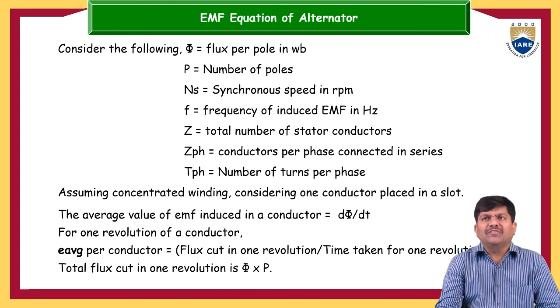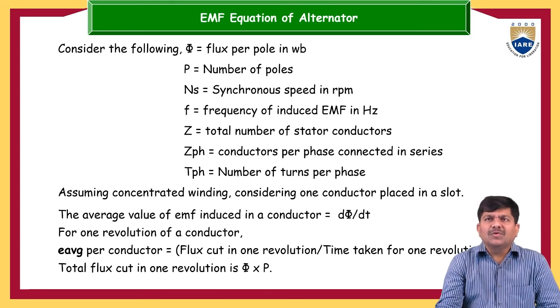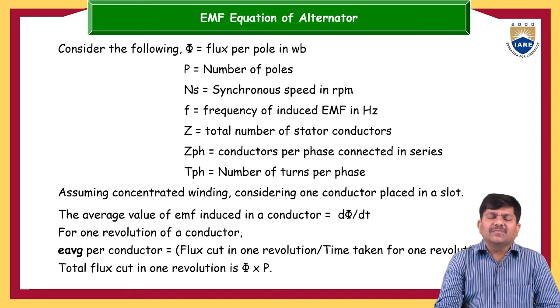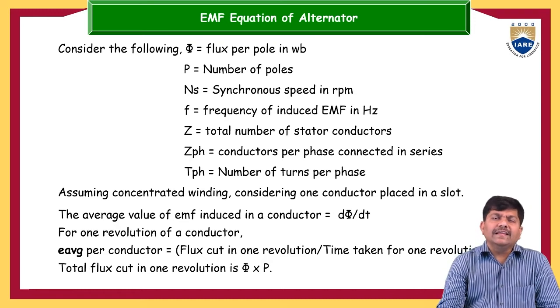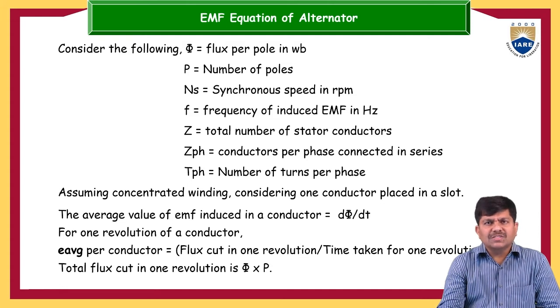F is the frequency of induced EMF in Hertz, Z is the total number of stator conductors, Z phase is the conductors available for one phase, and T phase is the number of turns per phase.